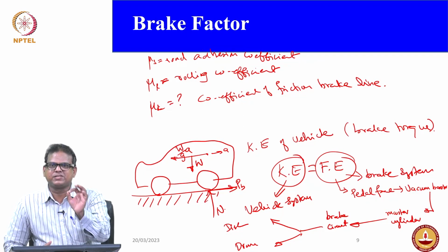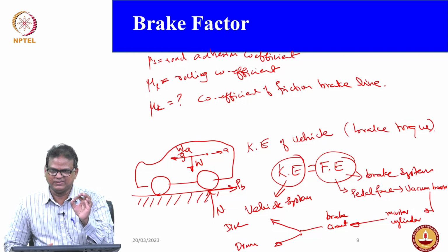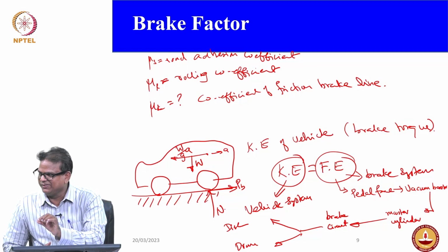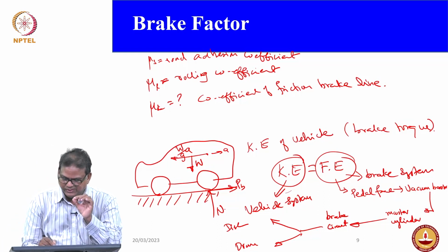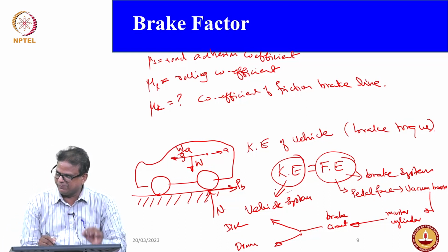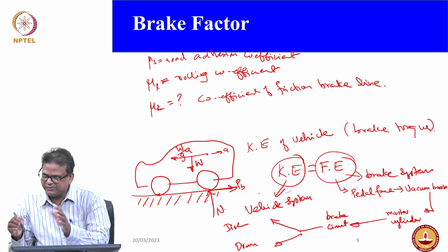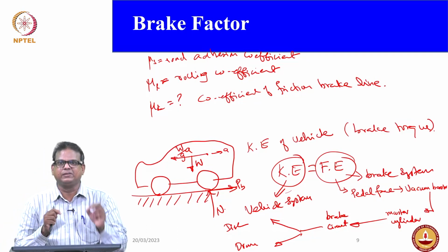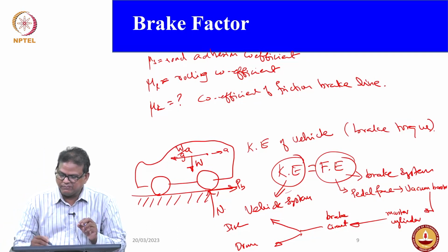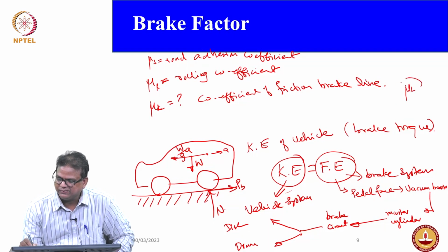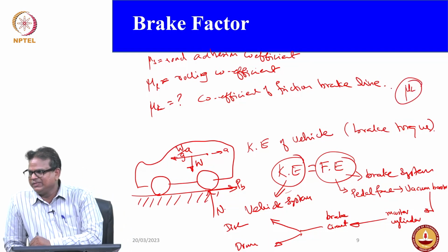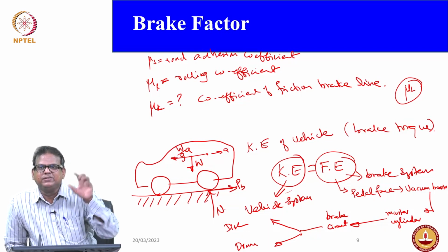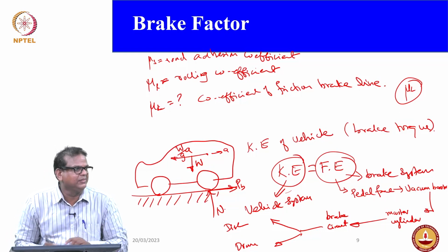That is based on your friction lining, the one generating the friction, no other component. So the entire energy from the vehicle must be matched by the brake system's friction energy through the friction lining. The question is, we never discussed anything about mu L. Did we? And how do we know what value we need to match this kinetic energy?